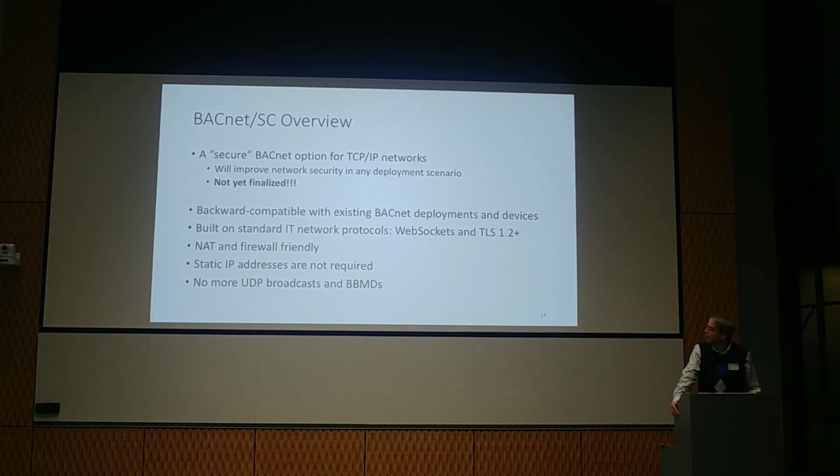BACnet SC is based on standard IT network protocols, WebSockets and TLS in particular. TLS is where we get the security. It is designed to be NAT and firewall friendly. We'll see what that means in a moment. You don't have to use IP addresses that are statically defined, but that does bring DNS into play. And finally, to the relief of many, we're not going to have any more UDP broadcasts or BBMDs.